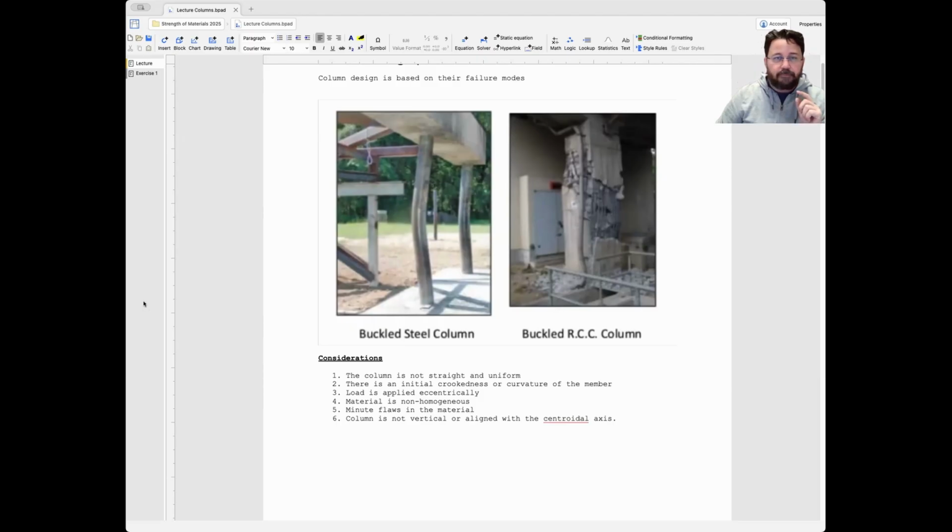Or there are inconsistencies in the material, let's say in the homogeneity inside the member, then that's a problem. So what happens when you buy steel profiles from dubious vendors, meaning they don't follow quality control? The additives used to manufacture the steel are not controlled by anyone. The processes are not controlled. Yeah, they produce a steel, but not the steel you need, with the properties you need. Remember that that's a spectrum. And then there is how the forces are applied on the column. So then you already know. With this you can go home and say, well, I know something about columns.